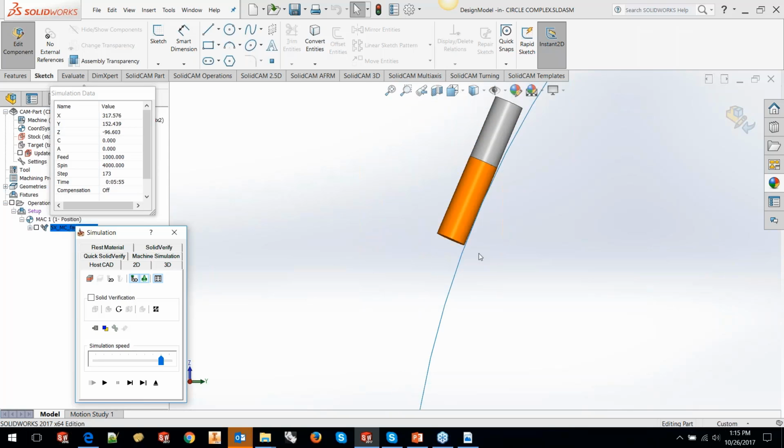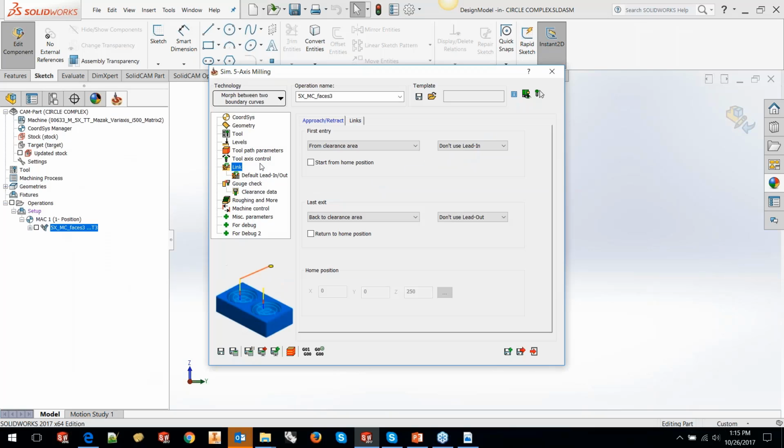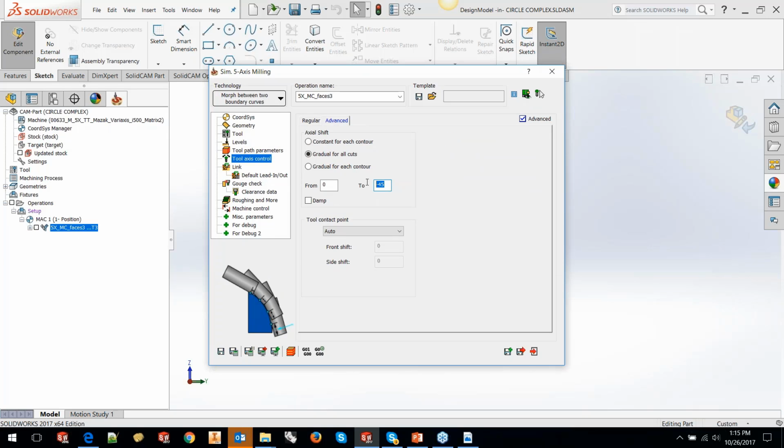It's no longer this. It's come somewhere here. So what it is actually doing is distributing the 45 millimeter cut length over the entire surface, so that the same point that cut on the top is not cutting the next pass. The next pass is shifted up by some amount so that it distributes that 45 millimeters over the entire surface. Shimshon, I will try it with a barrel tool, but not here online, and I'll let you know if it really does. I think it should still do the same thing because the functionality is the same.